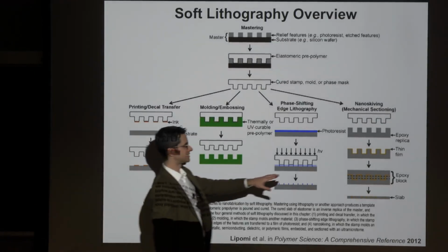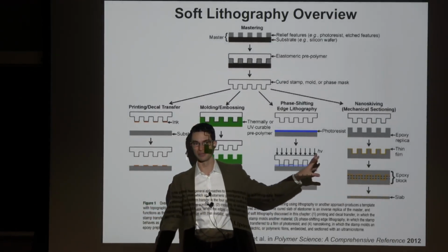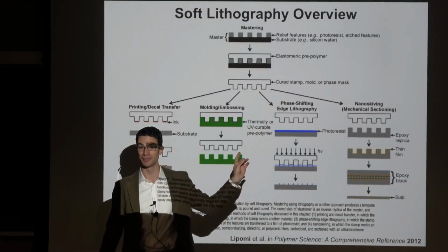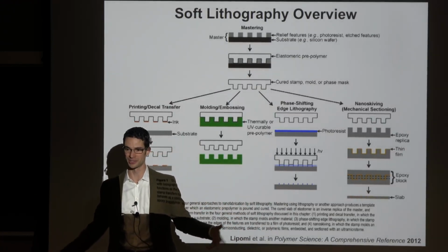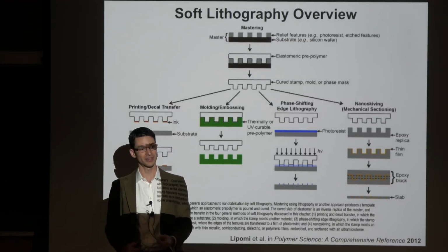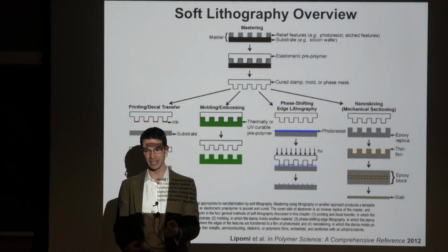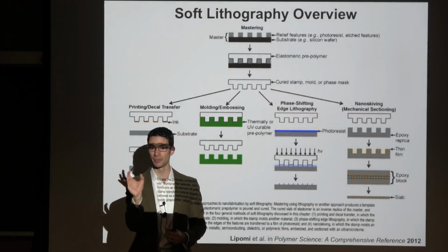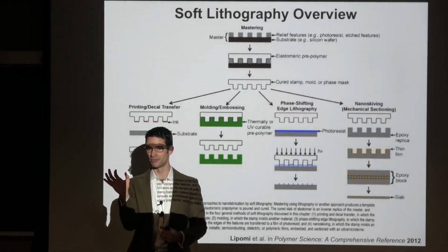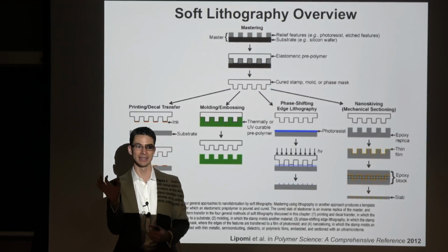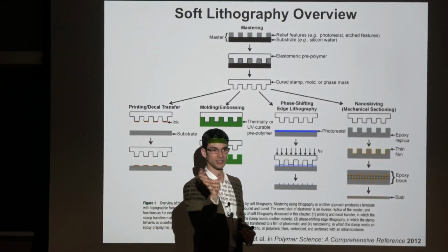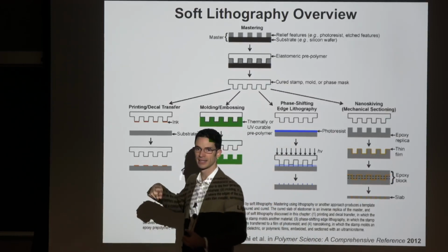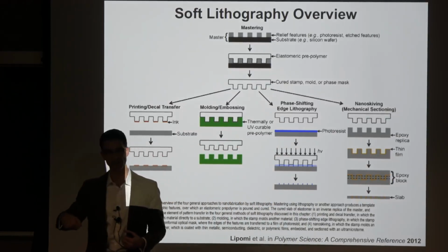You can also, and this is actually important, many of you will use microtoming not for fabrication, but rather for TEM sample preparation, which is what the technique was designed for. There are also oscillating blades, which have maybe a 400 nanometer amplitude, but vibrate at say a kilohertz or something. And as you move the blade back and forth, it's a little bit like sawing bread with a knife.